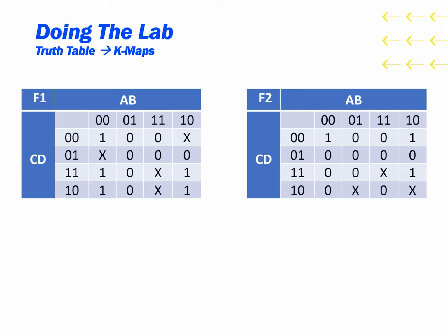When looking at the first K-map, the first thing I see is this lovely column here that groups most of our 1s. And then we can follow that up with a square to get all of our 1 outputs and finish the K-map very quickly. Our second K-map, we can use a looping group like this to get those out of the way. And another group here to map all of the 1s with 2 groups as well.